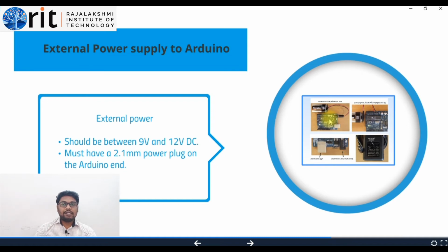Now we will discuss the different ways of powering, I mean giving power supply to, your Arduino board. I already told you the voltage range given as input to power your Arduino is nothing but a 9-volt power supply. Mostly we use 9 volt, but a 9 to 12 volt DC power supply is supported by your Arduino, so you can choose in that range for powering your Arduino board.